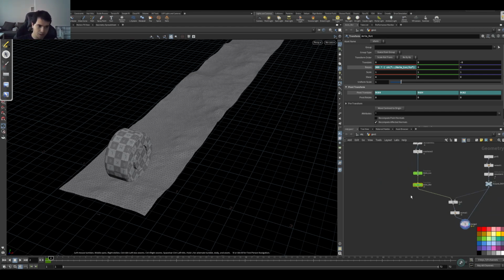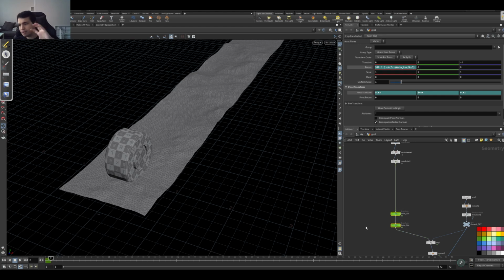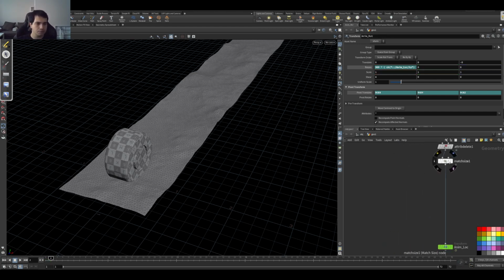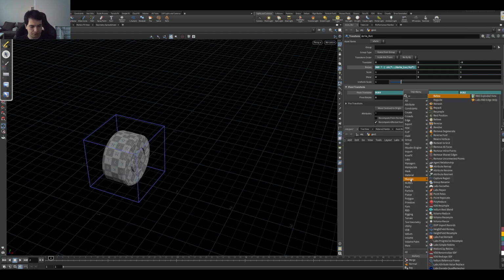As I said, we are working procedurally and we don't need to put our remesh or detailing parts after animation. We can put it below. So if I remesh here and animate after, I will be animating my remesh nodes and everything should work perfectly. So for trying out, I'm just starting from my mesh size node, okay? So I will just put a remesh here.